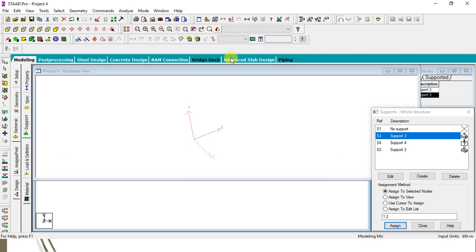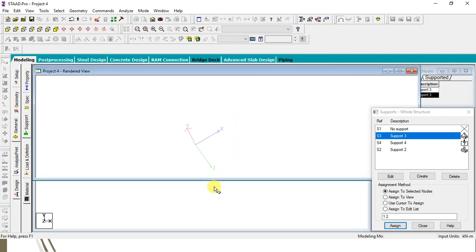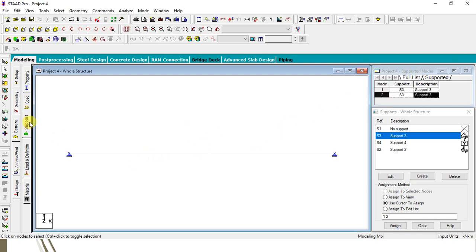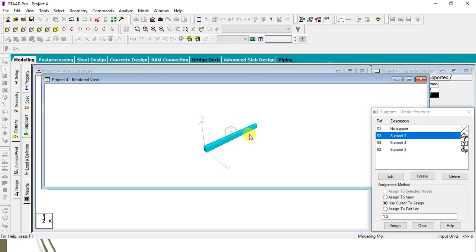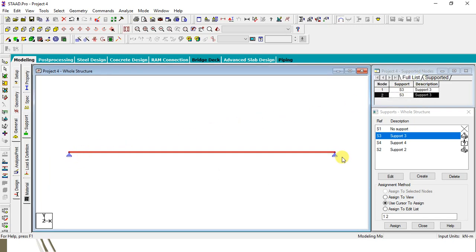You can check it through this 3D rendering view. We have to select the beam. As you can see here, the cross sectional dimensions are assigned to that beam, and you can see the support conditions are also provided. Okay, so do the practice of adding the different types of supports, and also go through the restrain and release conditions as per the support provided.